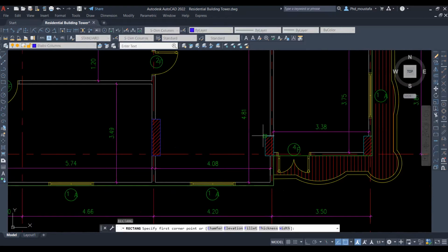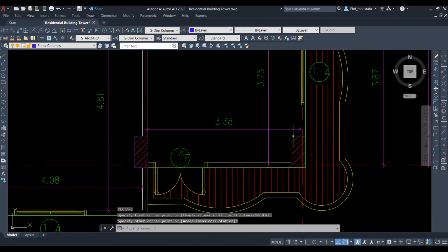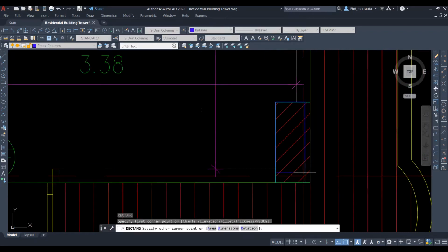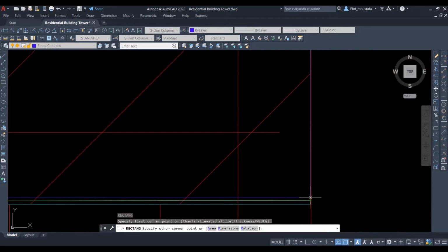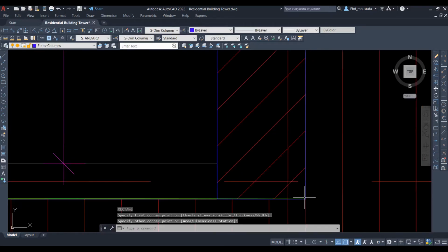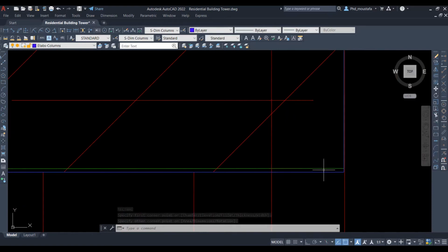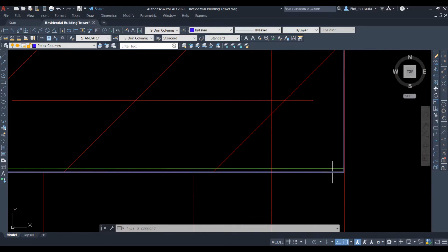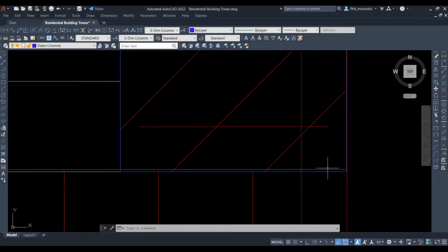So this could happen when the architect puts the columns and the wall in the same layer. This is a big mistake. So that's why you need to read and to focus. See this one. We also have a mistake here to be revised. See, the columns are outside and the slab is inside. But it can be fixed inside ETABS.